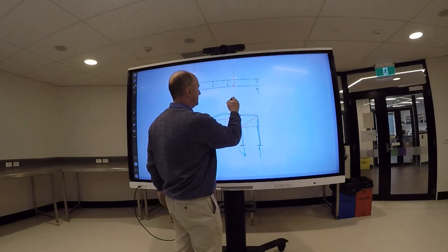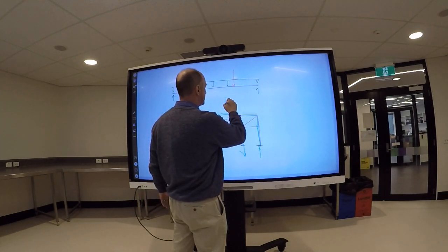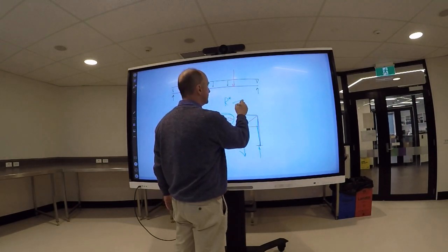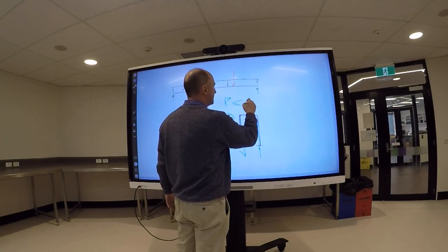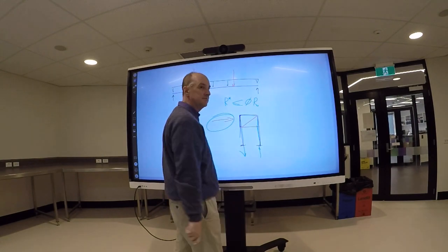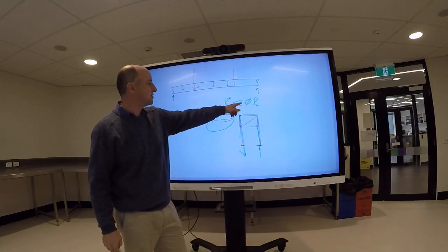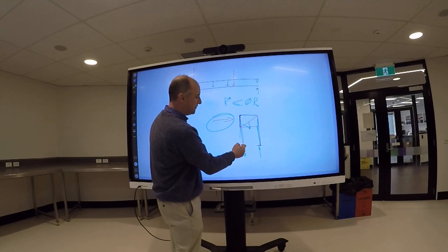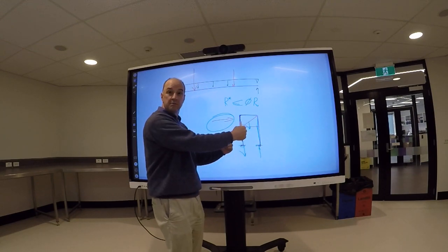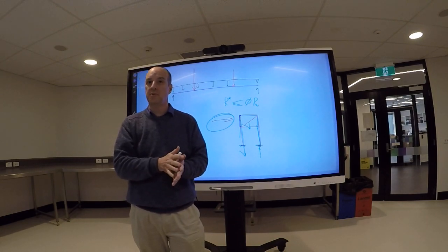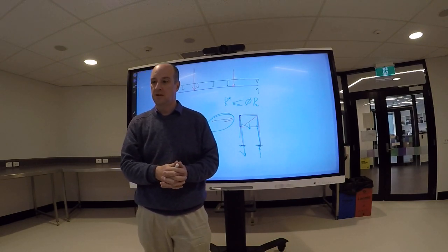Again, it's that, there's the overturning force, from whatever it is, has to be less than the phi times the restoring force, which is Ru naught. All right. In this case, the restoring force is the weight of the structure there, plus the weight of any footings like that, holding it down. Okay. Is that making sense? Okay.